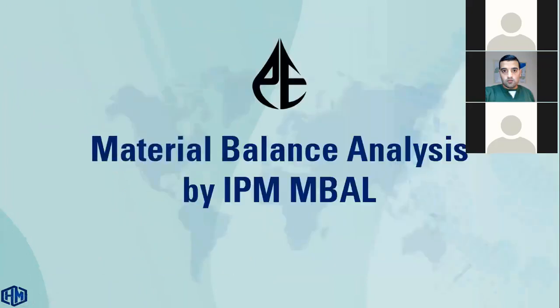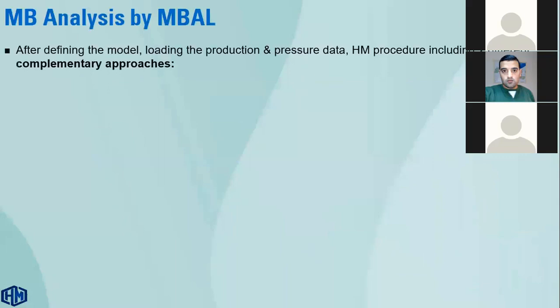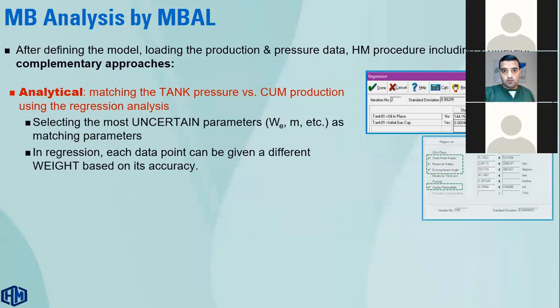Now we highlight the application of IPM MBAL software for material balance analysis. Typically, MBAL is used for material balance analysis based on the tank model. In MBAL, after defining the reservoir model and loading the production and pressure data, the most important step is history matching. History matching in MBAL typically involves two complementary approaches.